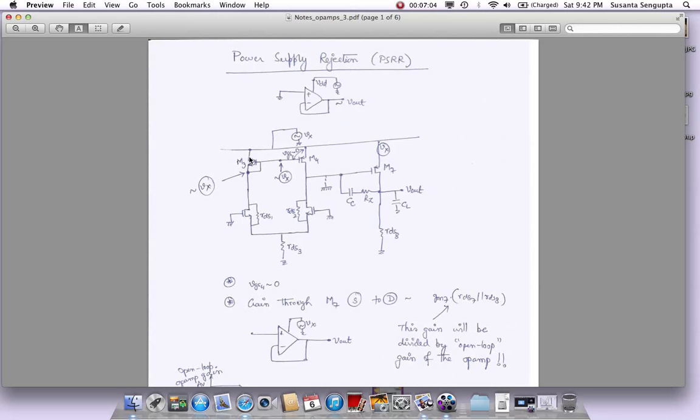So these two branches are not able to create any small signal current if the VDD moved by Vx. That is the first observation because of this connection here. Okay, so if it is not able to create any current, what happens to this node? Right, there is no current that's able to go and charge up these RDS values. This remains as kind of AC ground,